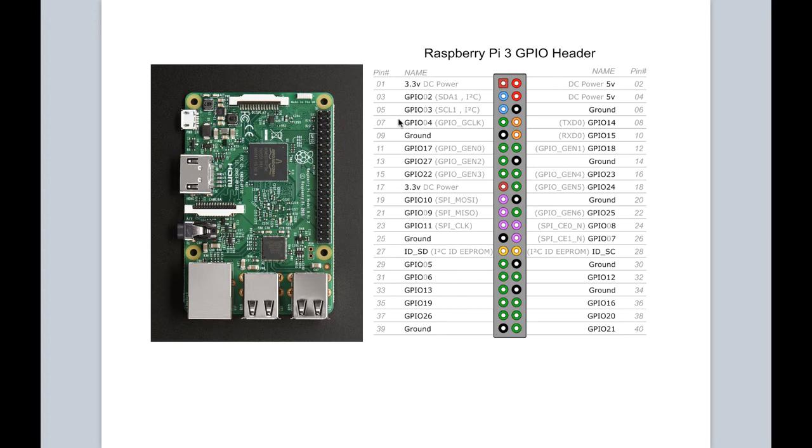Why you see two different numbers listed is because when you are interacting with GPIO pins programmatically in code, as is the case with Python, you can use the pin numbers, which is referred to as board mode, or you can use the Broadcom GPIO numbers, which is BCM mode. We will see this in action later on when we dive into some code with our circuit examples.